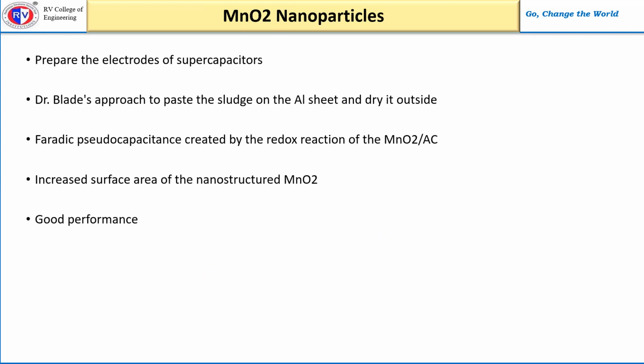Then coating it onto a supercapacitor. So preparing the electrodes for supercapacitors. The first step after preparing the nanoparticles is to prepare the electrodes for supercapacitors. Around 80 degrees Celsius, the combination of DMAC and polyvinylidene fluoride was agitated. Then the Super P and activated carbon were added to this mixture.